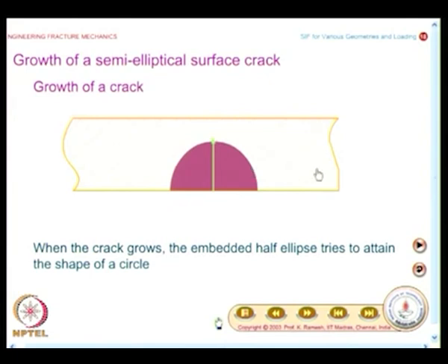So, what are the stages in this? See, you need to have a crack developed on the surface, then crack has a growth phase by some growth mechanisms, then it reaches instability. And what happens when it happens? It penetrates first through the thickness, because your fracture toughness is also lower and also your stress intensity factors are higher. Once it has reached the other surface, it is not that it starts proceeding on sideways immediately.